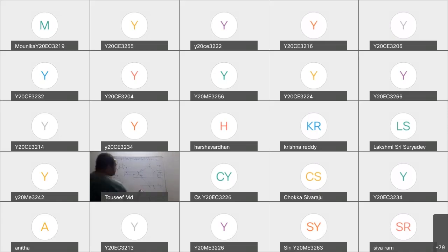Now you obtain point B and we join B with V. If I draw the vertical projector from A dash, it will meet the VB at a particular point A. Why? We know that A dash and A lie on the same vertical projector. Now I know A dash B dash is known, and the top view AB is known. Now I can take A as center, AB as radius, and draw an arc up to the locus of A. This becomes B1.